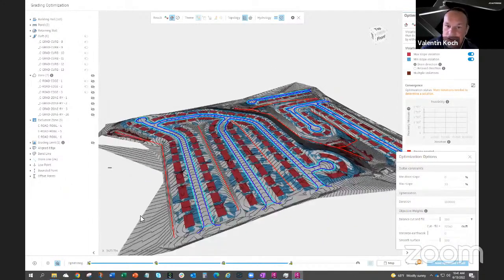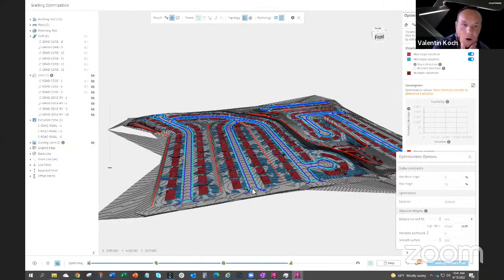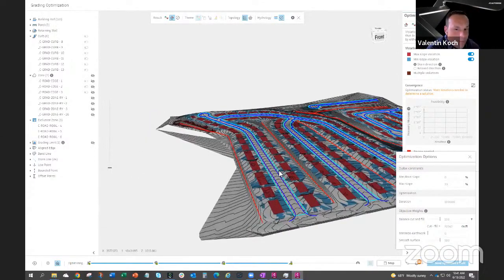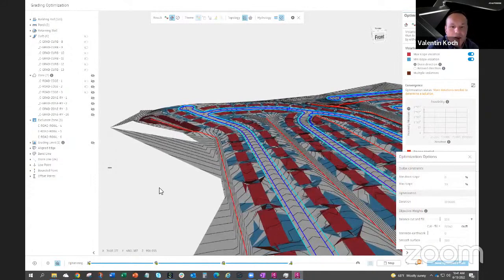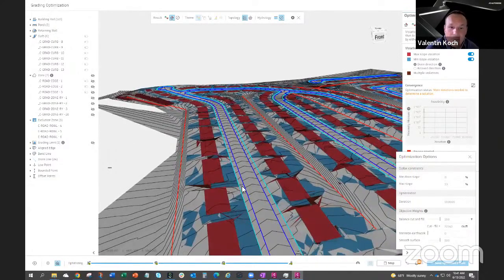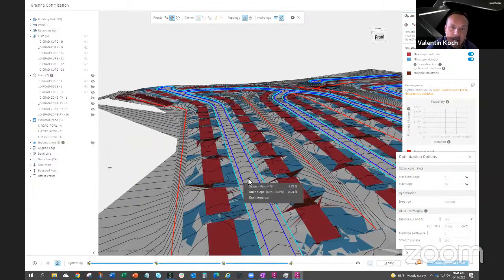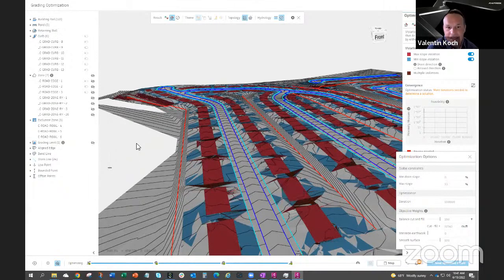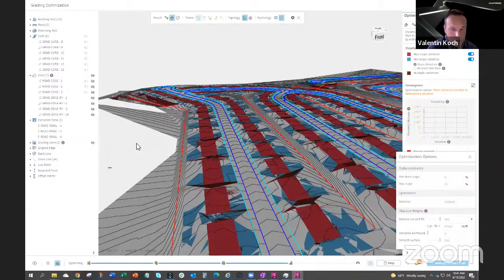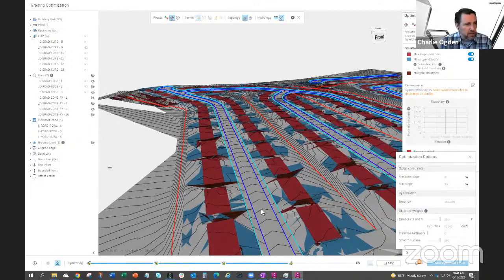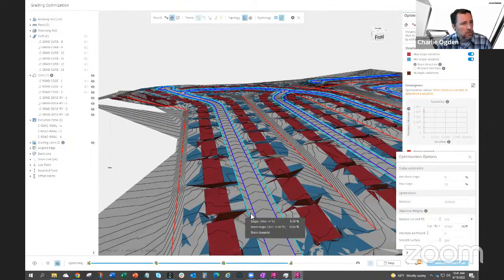Now, this is just another constraint, like any other constraint in the model, so sometimes they might be fighting with other constraints nearby. It could be that you see this boundary of the exclusion zone move a little bit, and the solver then puts it in place again. Just keep in mind this is because these bounded points are just constraints like any other, and the solver works on them. If you let it run longer, these should work themselves out and come back to what you had in the corridor.